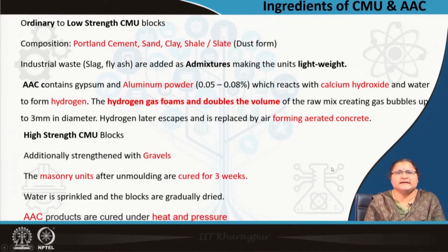Coming to the high strength CMU blocks, further gravel, that is coarse aggregate, is added, and they also require curing for 3 to 4 weeks. Water is sprinkled on the blocks, whereas, as I told you, AAC products are cured under heat and pressure.